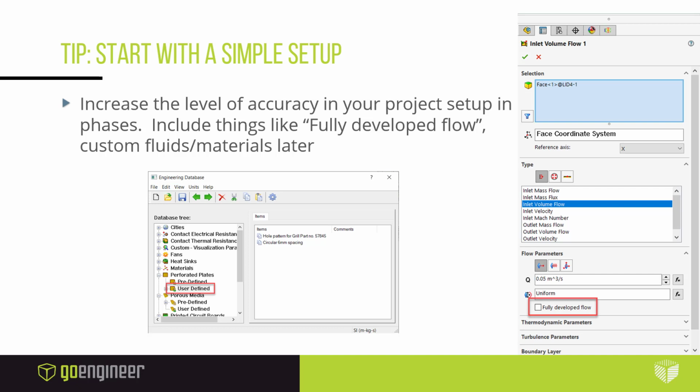If it's an internal analysis, define your inlets, outlets, and establish some engineering goals. Then maybe add some boundary conditions to represent fans or other more complex geometry. The goal here is to get a simple starting and working project that can then evolve into the project that you want to end up with.